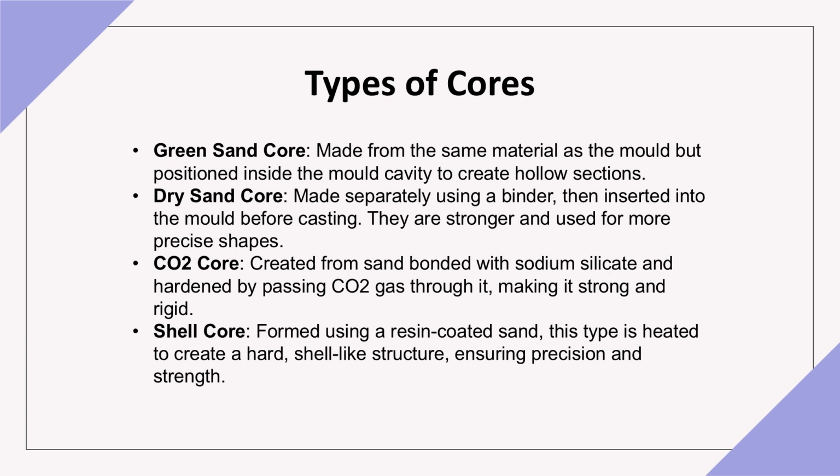CO2 core, created by hardening sand with sodium silicate using CO2 gas, making the core strong and rigid. Shell core, formed using resin-coated sand, heated to create a hard and precise shell-like structure for higher accuracy and strength.